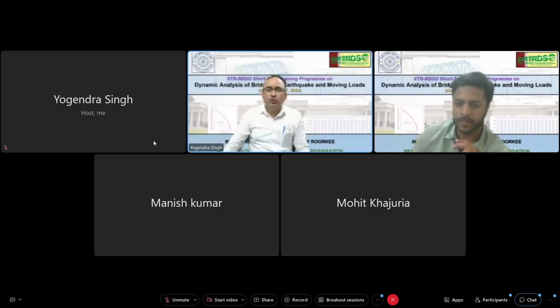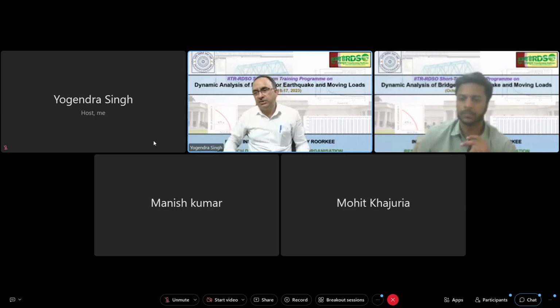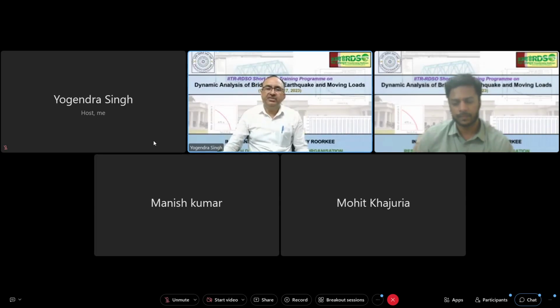Okay, so you cannot get those high frequencies. Even up to 33 hertz, obtaining the modes becomes very difficult. And there is debate whether it should be 0.01 or 0.03. There was discussion in the committee also. Some of the people were saying that it is not possible to analyze the ground motion or to get the response for a ground motion at such a high frequency. In that case, we can take it up to 33 hertz, or beyond 33 hertz we can take it equal to ZPA. If you can do it up to 100 hertz, good, it is better, but that will be difficult. It will be very difficult to obtain modes up to 100 hertz.